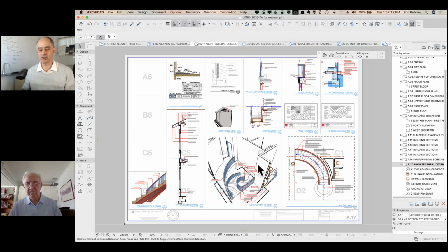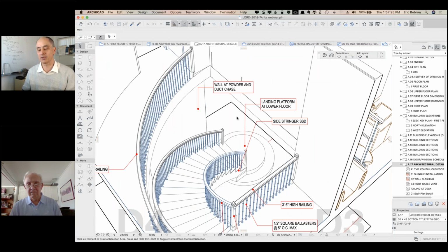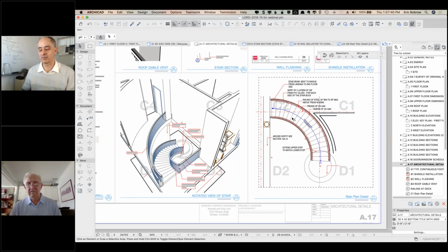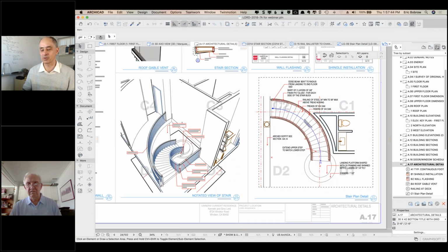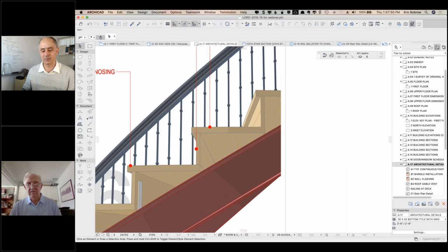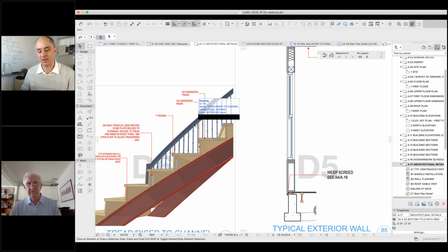So you're making good use of some of the 3D abilities of ArchiCAD in the documentation. So just taking a 3D view, saving it as a 3D document, and then adding notes on top of it. And this view would be live, so if you were to update the model and change some things, then this would stay current. And obviously, deriving some noted, enlarged views of the plan, of the stair, and I guess you have some more details of the stringer. So this is actually the structural stuff behind the ornamental cover.